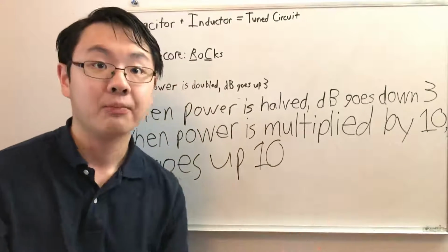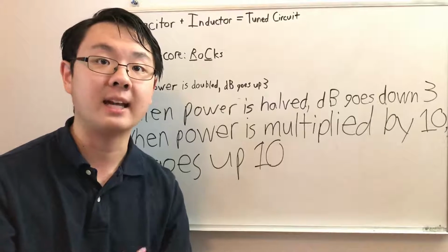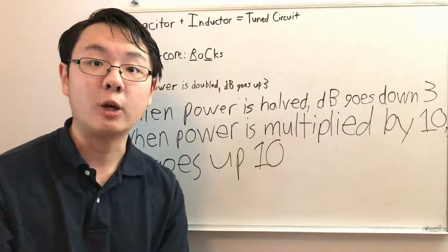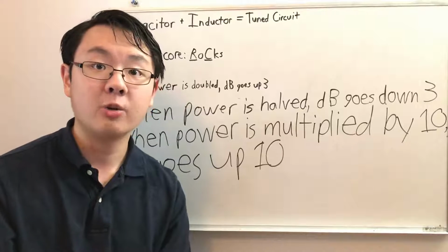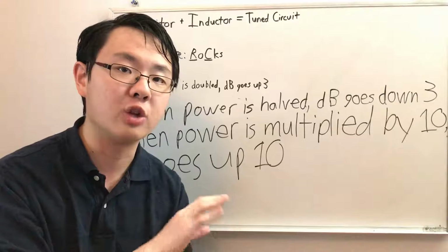That'll help you remember. Sometimes when you're soldering something onto a circuit board, the solder makes a bad connection and it doesn't connect the component to the circuit very well. This is known as a cold solder. That's what we call it. A cold solder, if you look at it with your eye, will look like a grainy or dull surface.